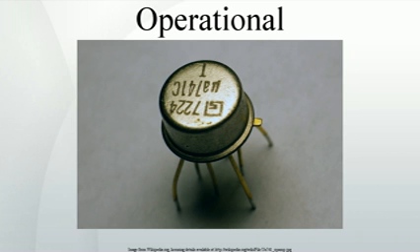Output amplifier. The output stage, Q14, Q20, outlined in cyan, is a Class AB push-pull emitter follower amplifier. It provides an output drive with impedance of 50 ohms, in essence, current gain. Transistor Q16, outlined in green, provides the quiescent current for the output transistors, and Q17 provides output current limiting.